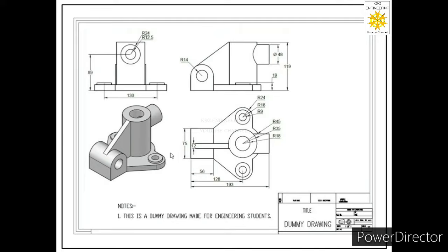A benefit of drawing isometric projection along with orthographic projection is that if reader gets confused with any of these projections regarding the geometry of the object, then in that case he can refer isometric projections. So isometric projection will give the reader more understanding about the geometry of the object. So isometric projections are especially helpful for the objects having complex geometry. So these drawings act as auxiliary drawings to orthographic projections.